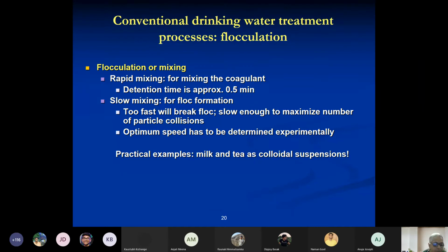It's natural organic matter. It's got tannins and lignins. Tannins and lignins are acidic compounds. They're natural organic. This is what we call natural organic matter. And the moment you add lemon, it acts like a coagulant and you get flock formation and settling of the flock at the bottom.